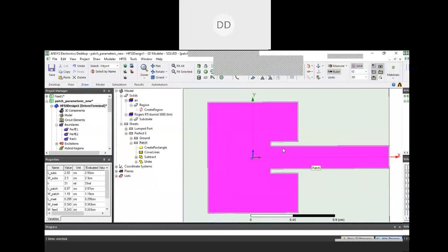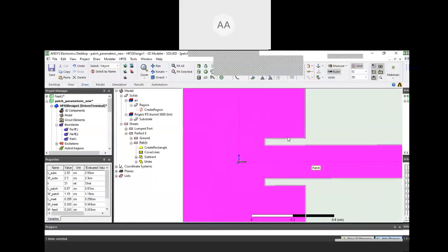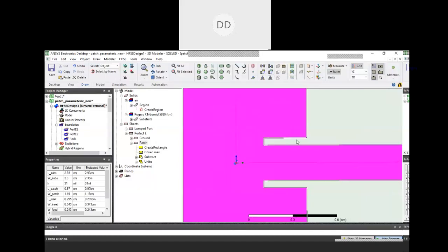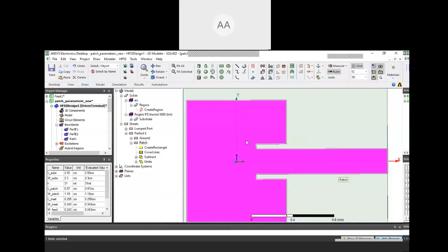Let's just take an example. Here we are getting, let's say, one gap here and another gap there. We can say there is a small amount of capacitance on this side and this side. So we model this gap with the help of a capacitance. This line has capacitance and inductance, and the patch, as a resonator, is an RLC. Then you have to connect them in series or parallel depending upon the configuration, and finally get there.